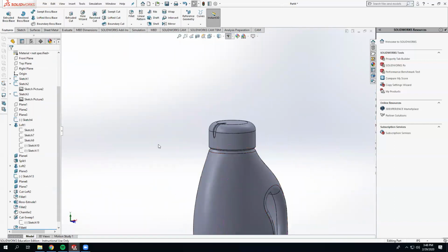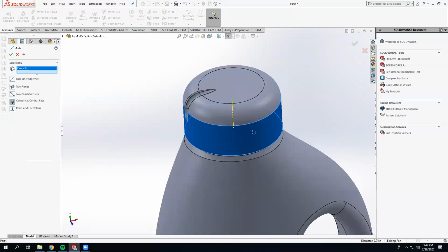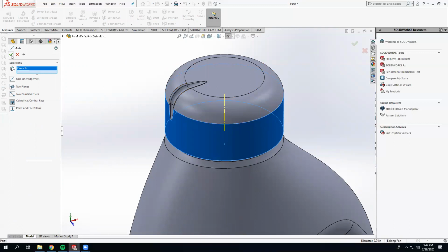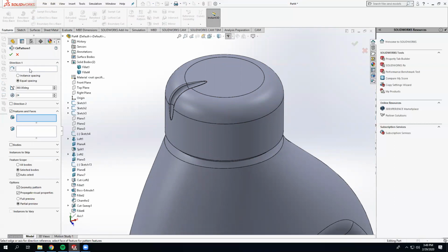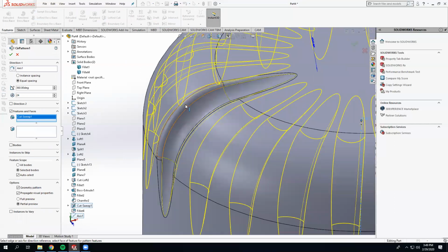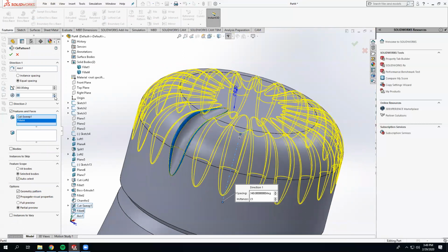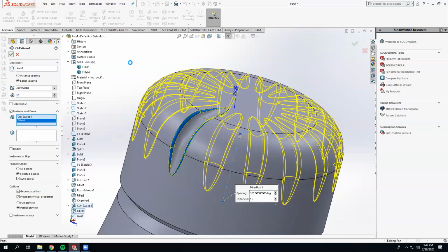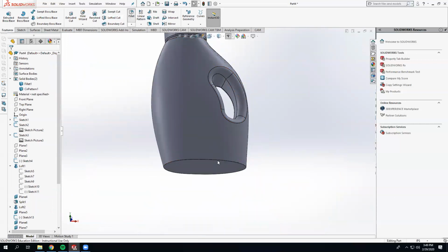And then yeah, that's for example how you create that cut. Then I will do reference geometry, create an axis because I want to pattern that cut, right? So I selected the cylindrical face because that's a cylinder, and now I have an axis, and then do circular pattern. Click on the axis that I just created. Features, in this case, I'm replicating this feature cut into this cap, so I could do features and faces. And then this. And there is slightly touching, so I could do less. And then add some fillets here at the bottom.